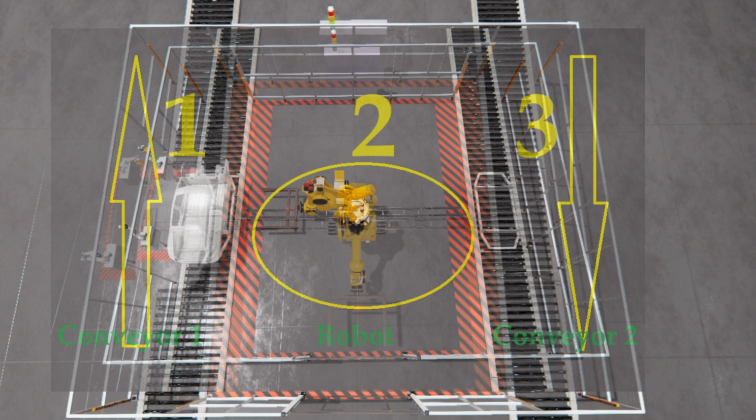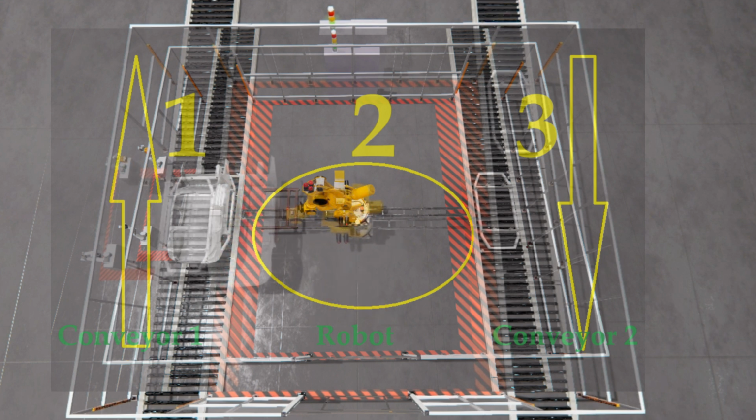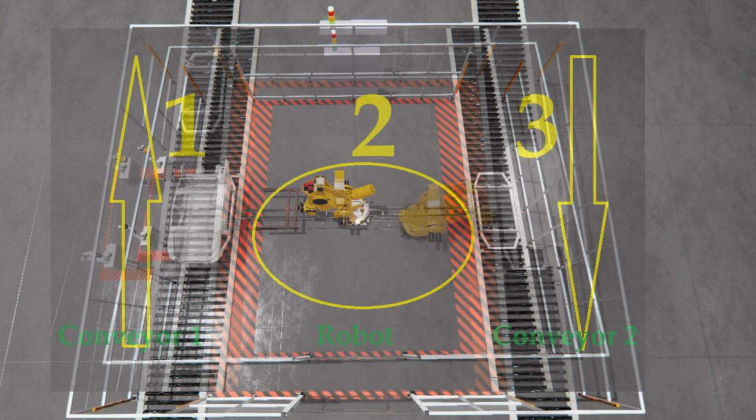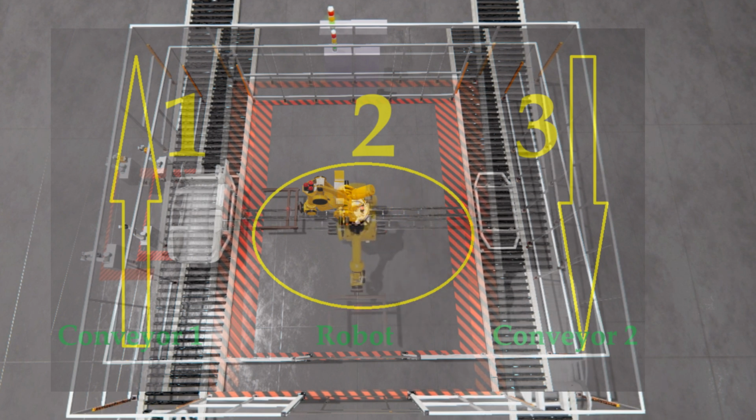If the hood is not present, then the Conveyor 1 sequencer will wait until the car body is picked up by the robot and moves to the home position. The camera returns to the home position and the carrier is sent out of the inspection station. The robot sequencer 2 will pick up the car body without the hood or defect and transfer it to the empty carrier on the returning Conveyor 2.